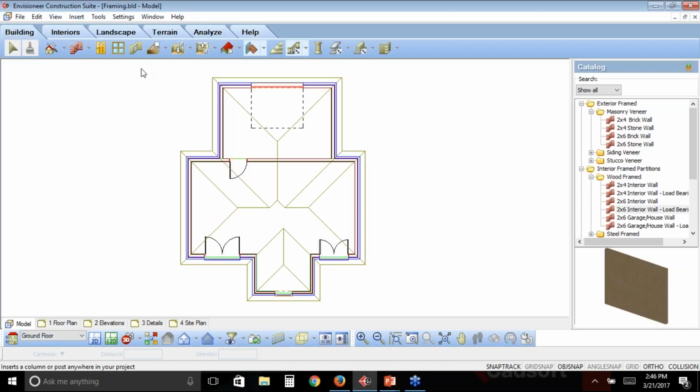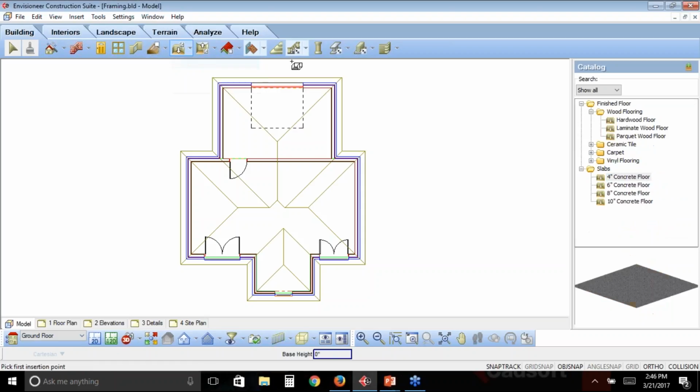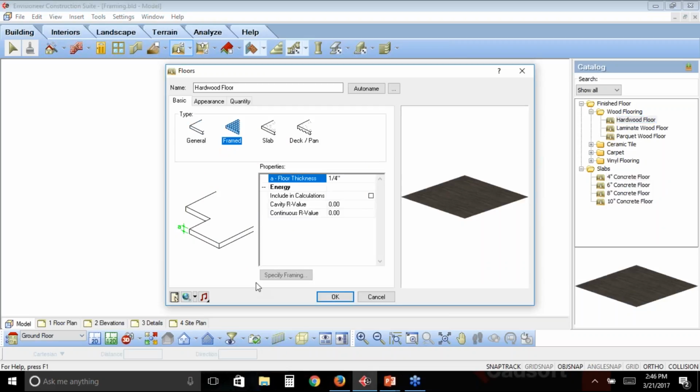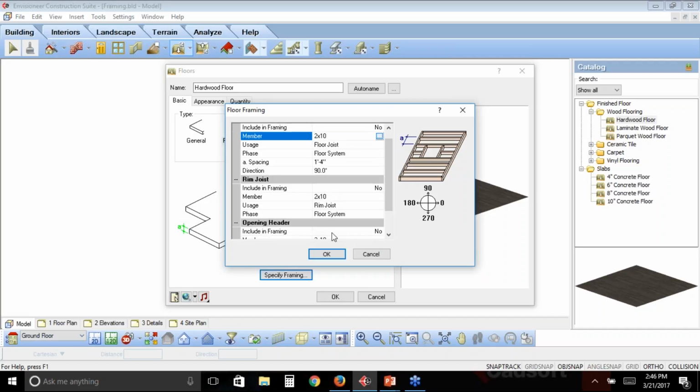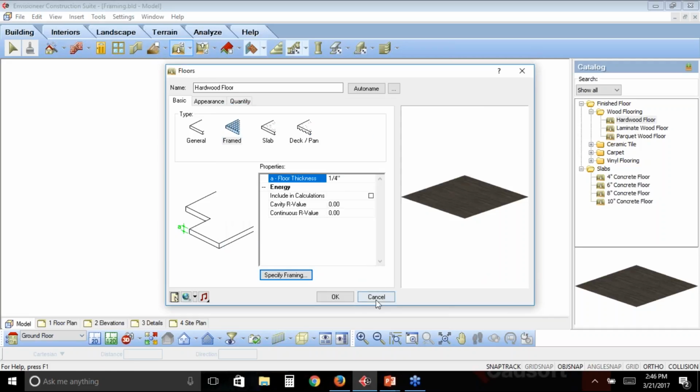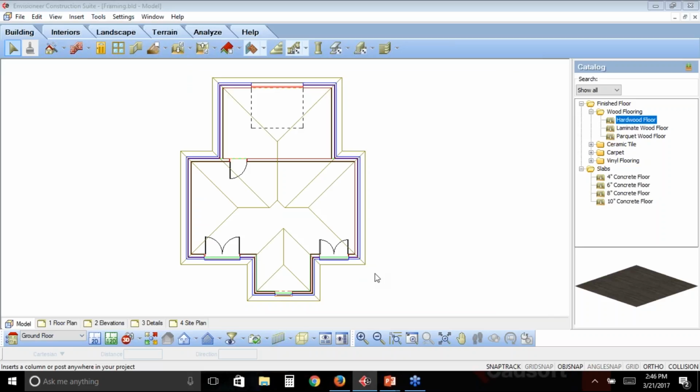When you're framing your floor, I highly recommend using the structural floor tool. It allows you to place the floor joist, the subfloor, the sill plate, and the sheathing in at the same time. If you're using Pro Architect, you'll be using just the floor tool. And the floor tool, if I look at it, can have some basic framing options to it as well. Basically just letting you lay out the 2x10s or your floor joist and your rim joist in a header. They won't be individual members that can be manipulated. You won't have the option like we did to insert that bearing line.